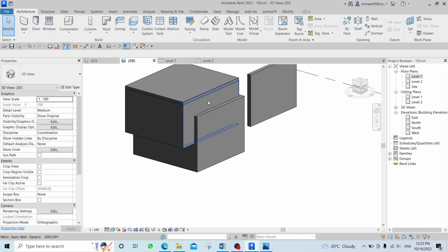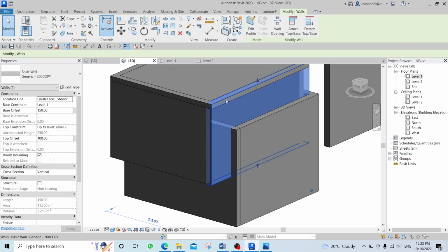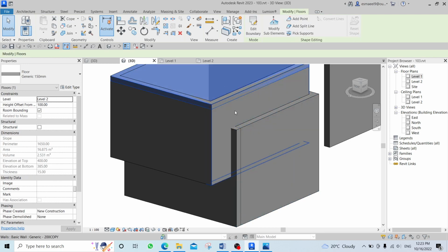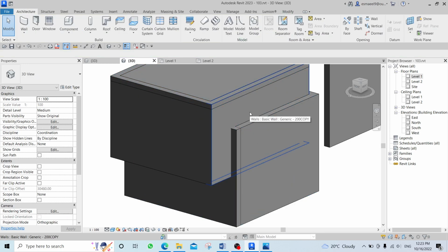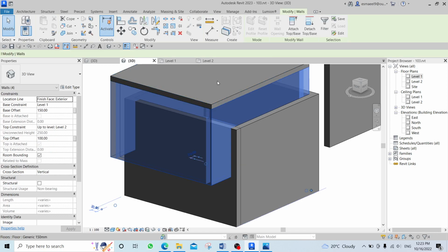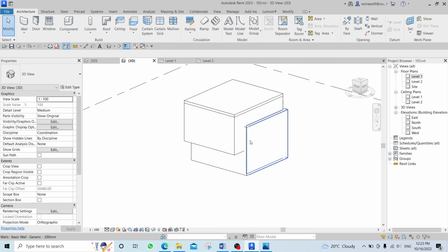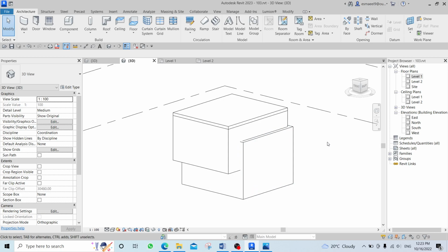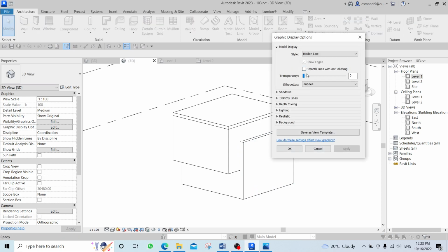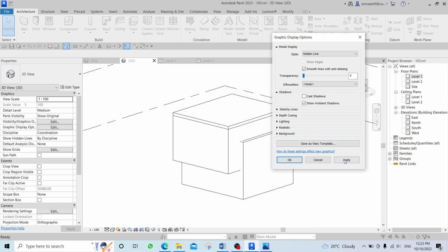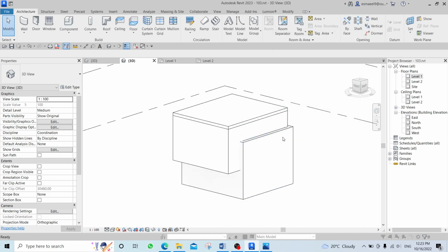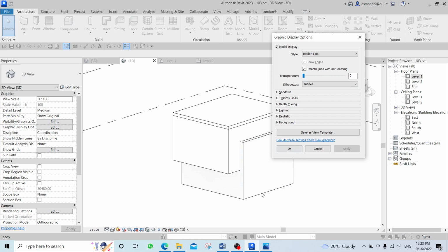Let me select all and detach. Our walls were something like this. There was an intersection between our wall and our floor. What we did was hover over one of the walls, click on Tab in order to select all the walls, click once, and then attach top base, clicking on your floor. So this was actually what we did. I don't think it will be a problem to understand that. So good luck.